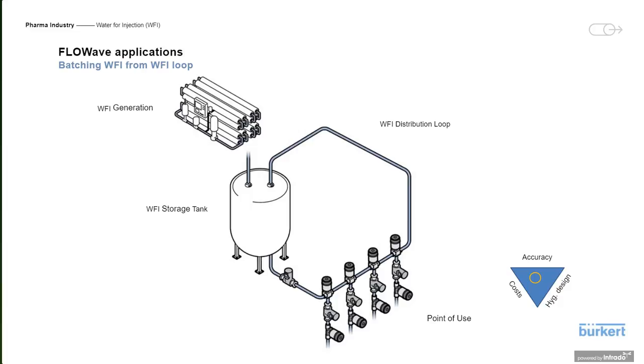The ability to utilize FlowWave with a comparable smart valve allows you to decentralize control and put it where it can make the most benefit to your overall system, even at the device level, to have the valve and the flow meter controlled together. It takes load off your PLC. It also allows each loop to make the decision at the appropriate level. And we'll talk more about that later on in the presentation. One thing I will point out too is that our element topworks do come with built-in PID functionality, which would really allow you to do the decentralized automation.